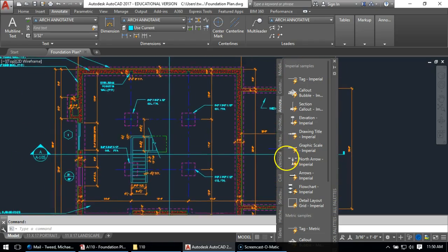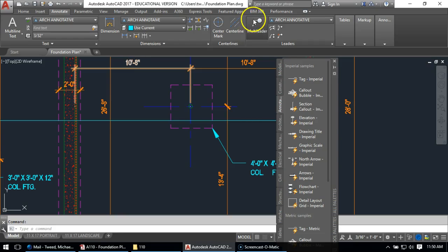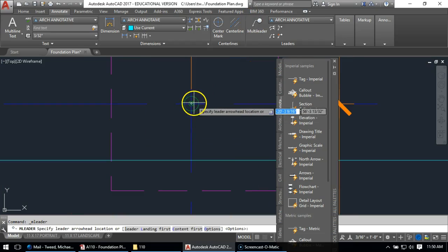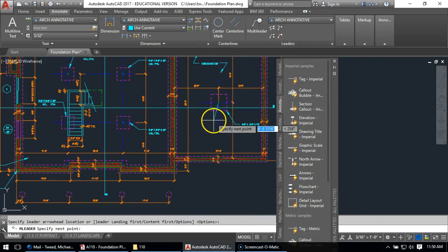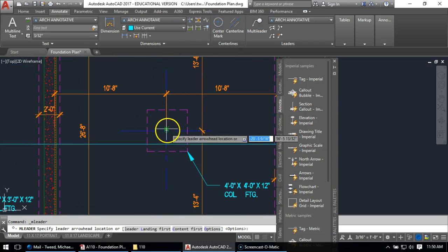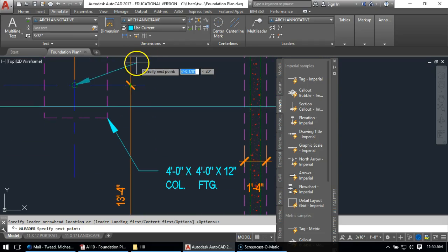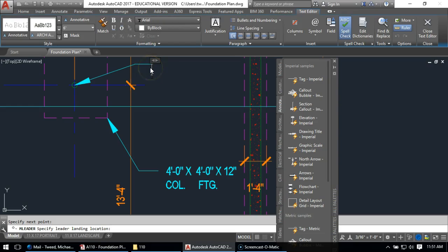Then I've got to dimension the columns. Find a good spot. I've got some room over here, so I'll dimension the columns here. Again, maybe I'll just sort of eyeball it. Actually, why don't I go this way? The exact placement doesn't fully matter, but when you can get alignments up, it sometimes helps make the drawing read.